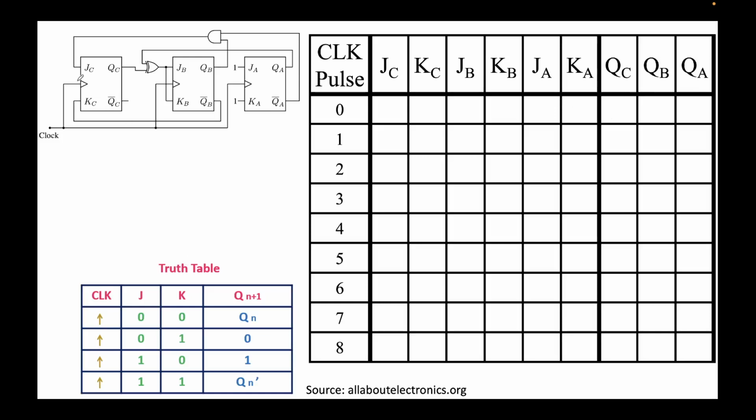Now, all 3 flip-flops are synchronous, since all 3 have the same clock. Secondly, all 3 are positive edge triggered. There is no circle here, which would indicate negative edge triggered, hence this is the truth table for them. Finally, we saw the initial state is 0 0 0, and the rest we don't care about. Now we need to go up to further clock pulses.